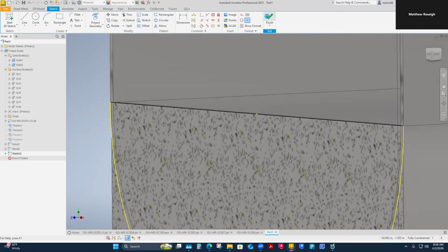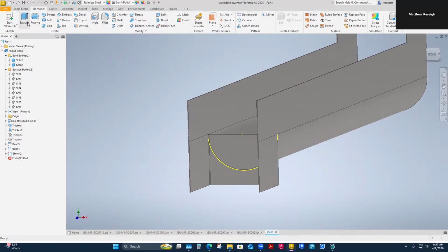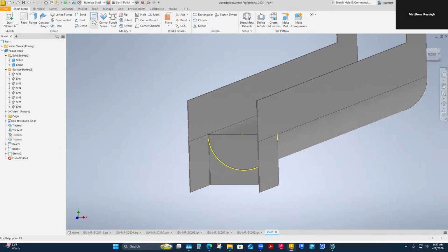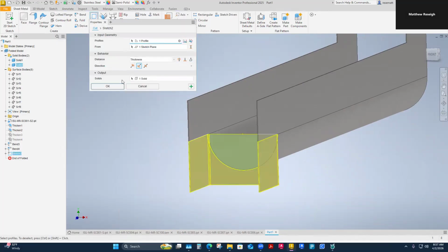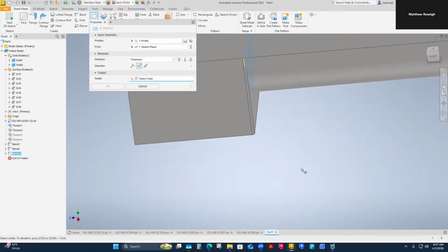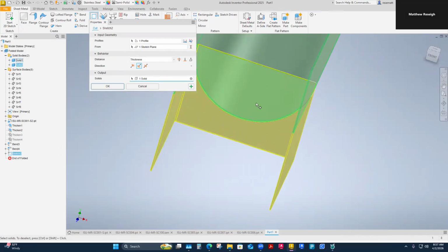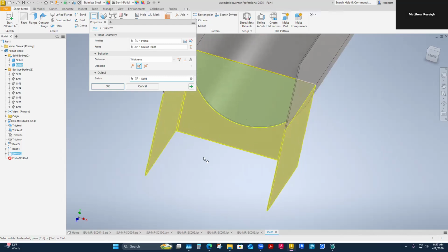And then I'm going to say finish that sketch. I just need to reperform that cut. It's not right or wrong to go either way. A 3D model extrude cut or a sheet metal cut is what I'm going to use, just because it's preloaded to do thickness, and it already selects the solid that I want for me. If it didn't, I just need to make sure I select the solid that I'm going to cut. My profile has been chosen because it recognizes it. It won't even let you cut if the profile is not closed. So if you're not getting the cut function to even recognize a profile, then you have to troubleshoot and look for a closed loop on the sketch.